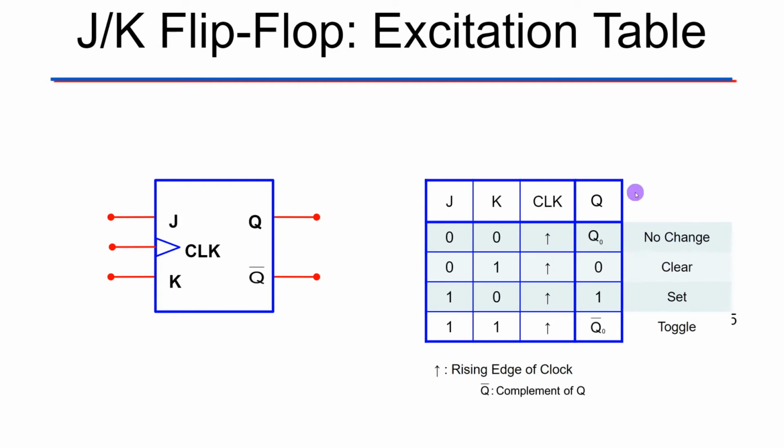So instead of having a 4-bit counter go from 0 to F, if we want it to look like a decimal number, base 10, then we say, just kidding, when you get to 10 or 1010, go ahead and hit that clear button and 0 everything out, regardless of whether you're about to go to 11 or whatever. And then set is the same thing, but the other side, where preset is usually what it's called, setting to 1. So this is rising edge.